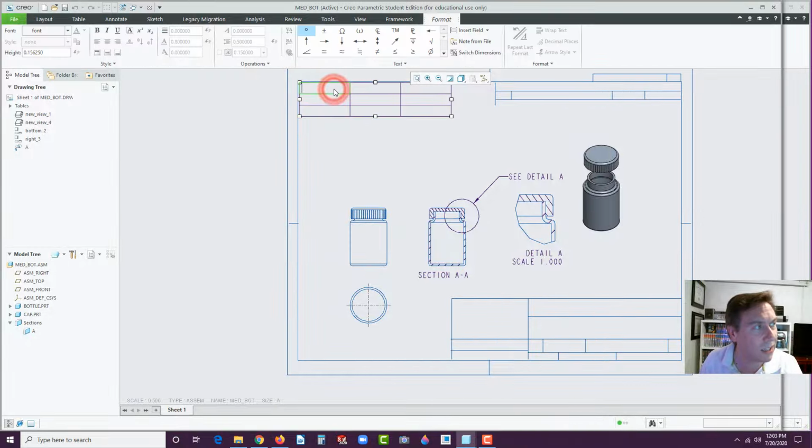Now you could double click in here, and we'll go ahead and type in part, and we'll put in pound, part number, double click in here, name or description you can put in. And then this one is going to be QTY for quantity.